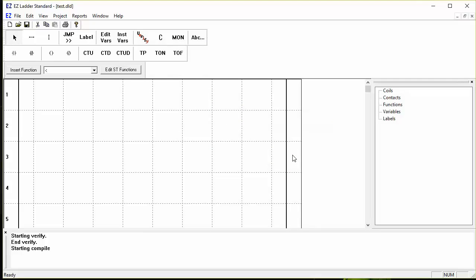The output window on the bottom of the screen is where status messages and programming information is displayed. Any errors will need to be addressed before the program will compile. When EasyLadder is started, it will open the Edit menu. This is where ladder diagram projects are created. When downloading the program into the target, we go into the Monitor or Run mode.